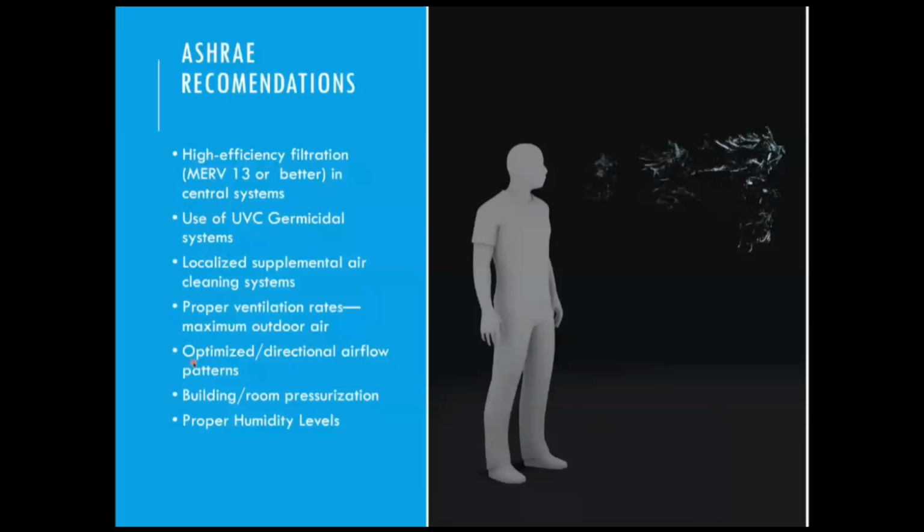And then the other one, interestingly, is the humidity. Humidity plays a role on both sides. It plays a role in people. If the humidity levels are too low, that affects the functioning of the lungs and nasal membranes in dealing with things that are breathed in. Also, as I mentioned before, the droplet nuclei start to get smaller quickly as they leave the 100% humidity, 100-degree air in your lungs and you come out into the ambient air. So the lower the humidity level, the more quickly they will get smaller.